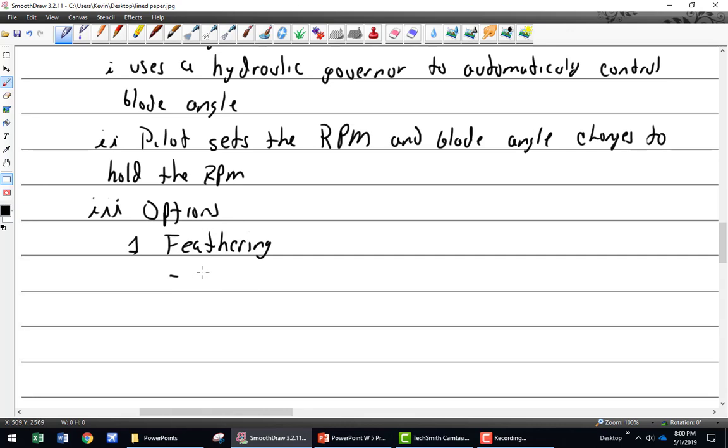You're talking auto feather, right? Yes. Okay. So we'll talk about auto feather later, but right now, auto feather is actually a function where, because it takes a long time for a pilot to register which engine has gone, there's an engine problem, it has gone out, and react to the feather. And if you're just taking off, that's when bad things happen. So some aircraft have an auto feather where it senses the loss of thrust and automatically feathers just that fast.